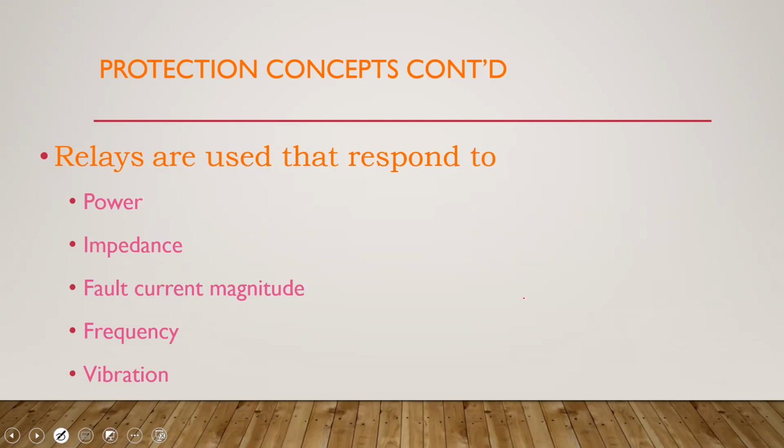One of our independent power producers had the vibration going for a little while on its generator. I can't say whether or not it was ignored or they didn't understand what was happening, but they kept operating and ended up losing the generator. So the system was down some 30 megawatts with that generator out.